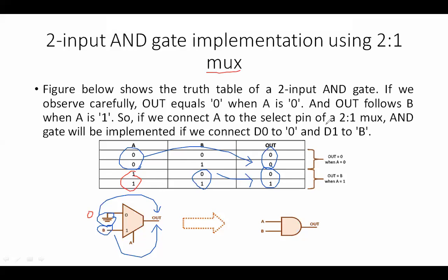So that's why this mux and demux is a very special logical circuit, which not only helps us in selecting the inputs, but can also help us in getting logical gates implemented, multi-purpose. So what you can do: first, have the truth table.